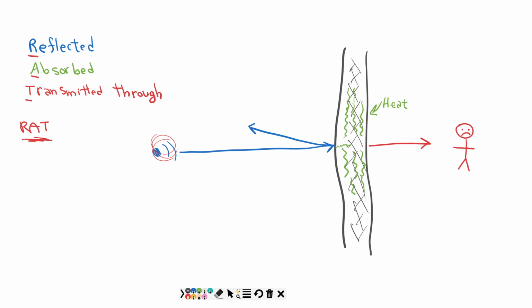So there are materials that are very good at reflecting. A painted cinder block wall, for example. 99% of the sound that hits that is going to reflect back in. It also has tons of mass. It's very, very massive. So mass is really good at preventing the sound transmission. So, we can have something that absorbs like heavy drapes, rigid fiberglass. So this doesn't have to be something like concrete, but I could have this, whatever it is, filled with highly absorptive materials and not a lot gets through.